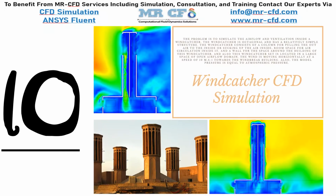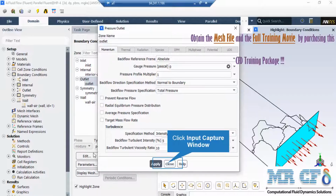And finally, in the last project, we simulate the airflow and ventilation inside a wind catcher. If you click on the outlet boundary, you can see that the type of this boundary is defined to be pressure outlet. Just like the previous slides, if you click on the edit button in the appeared window, the most important point you should pay attention to is the gauge pressure, which has a value of 0, which means that our airflow exits the computational domain to the atmosphere.